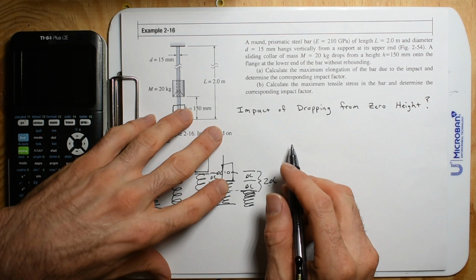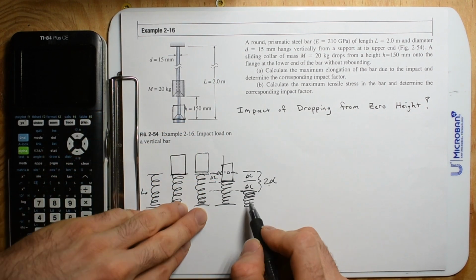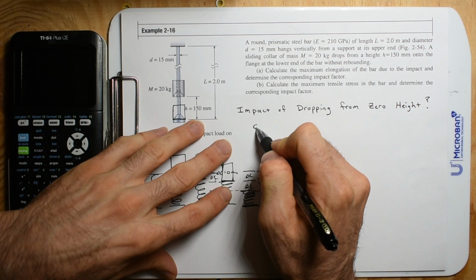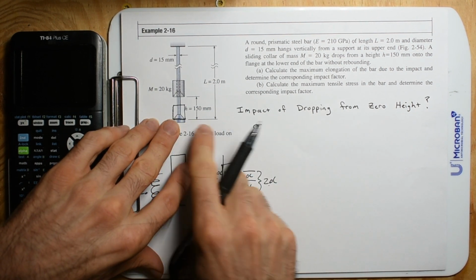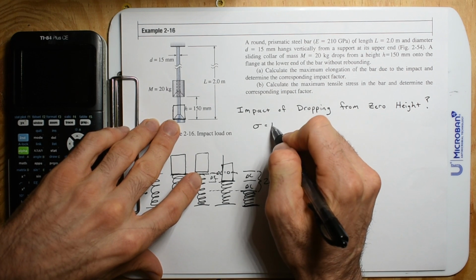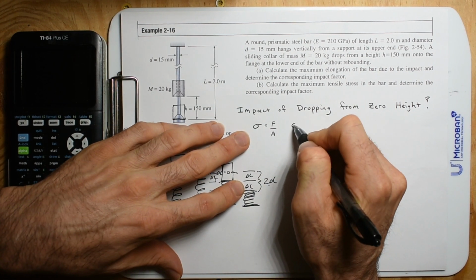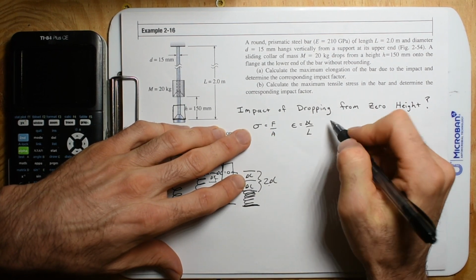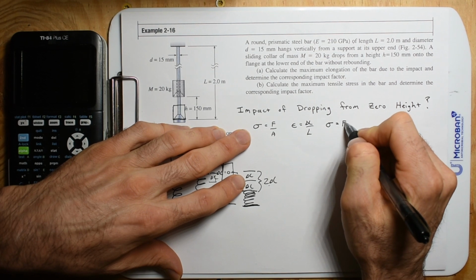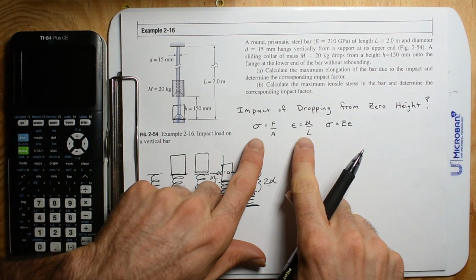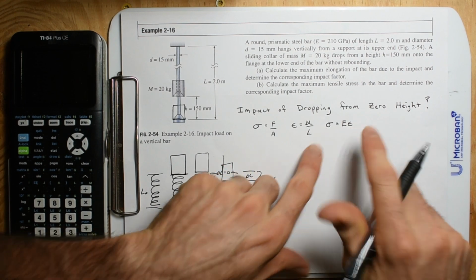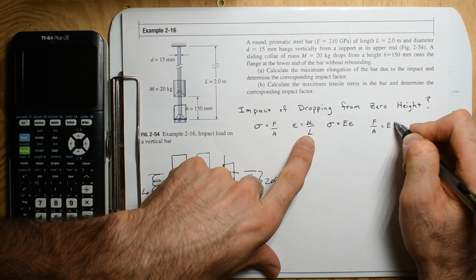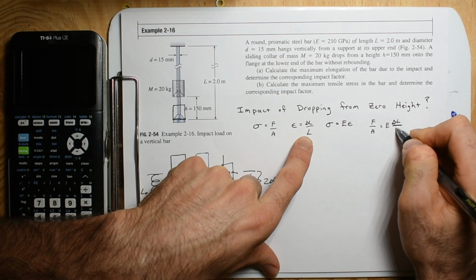Okay, hell yeah. So before we do energy, the first question is, what is this initial change in length? We're dealing with mechanics of materials, so you have to write all these equations out. I would write them every time. Stress is force over area. Strain is change in length divided by length. And the relationship between these is stress is modulus of elasticity times strain. Now we can take these two and insert them into here, and so we get F divided by A is modulus of elasticity times change in length divided by L.